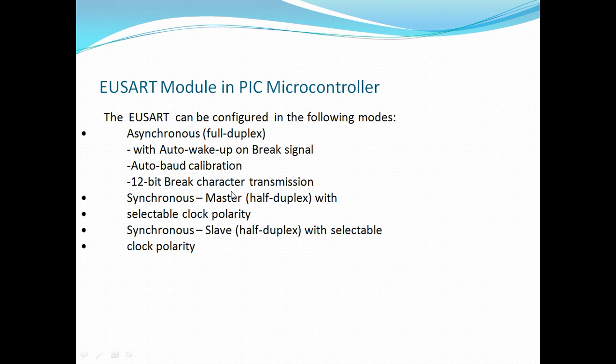Okay, it may be master, it may be slave, that can be configured in this PIC microcontroller. 8051 supports only asynchronous mode of communication, but PIC microcontroller supports both modes of data transfer, asynchronous mode as well as synchronous mode.